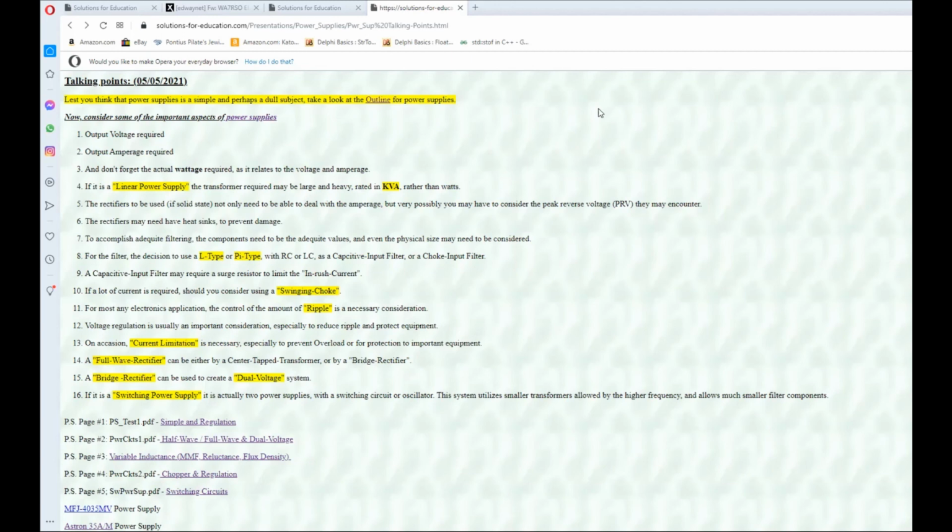And that's a current on the outside of the core? The core itself would actually produce eddy currents, yeah. So the higher priced transformers were thinner than the other ones, and they're actually glued together with shellac and such. Okay. But as you go up into higher frequencies, they couldn't use iron laminations. And it had to be soft iron because soft iron does not retain a magnetic field. They had to be careful of that. Gotcha.